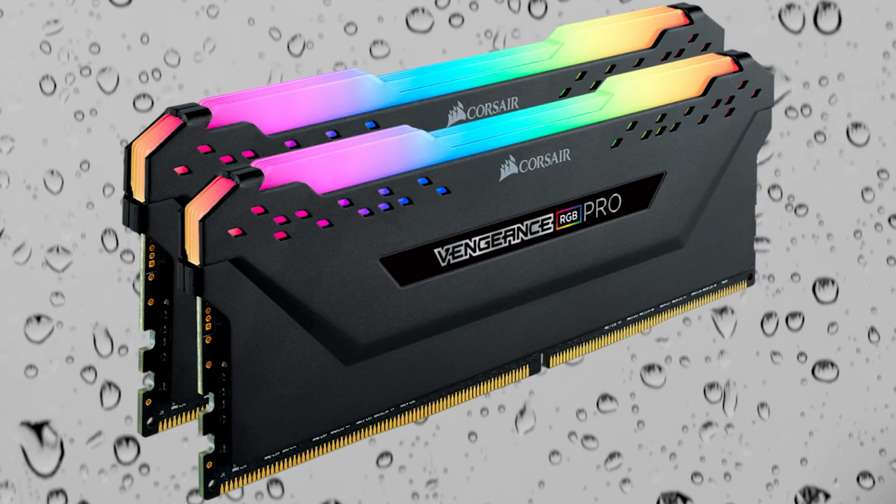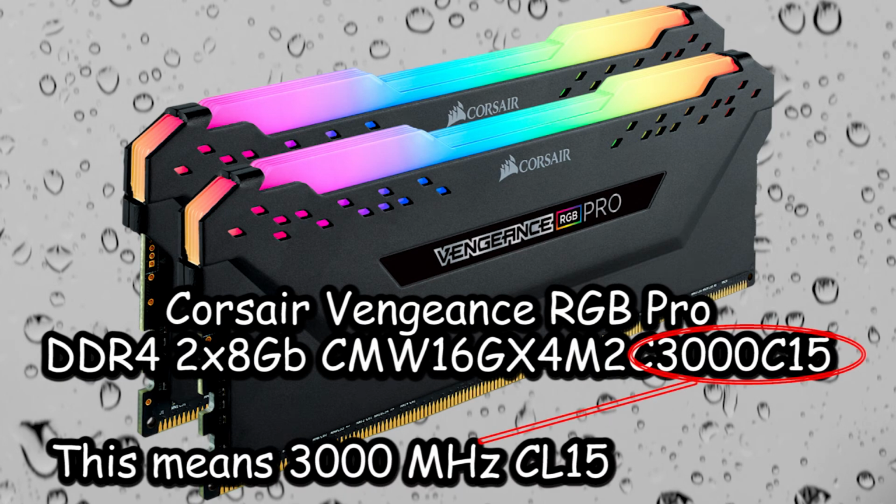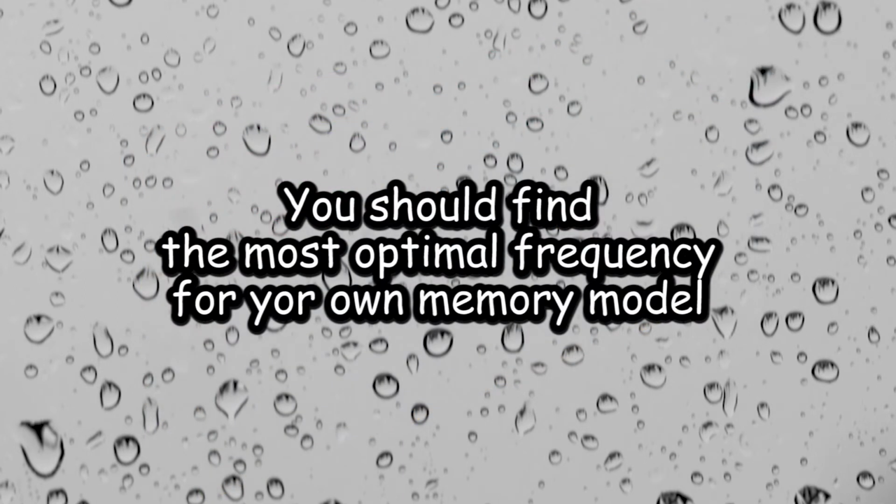Secondly, to achieve the best performance, you should find the most optimal frequency for your memory model. If it has an XMP profile, it doesn't mean that this frequency is the most optimal for the certain chips this model is based on. Sometimes the most optimal memory frequency may be higher than the frequency of the XMP profile, but sometimes it may be lower. Your goal is to find the frequency which will let you decrease main and secondary timings as much as possible and provide the lowest overall memory latency.